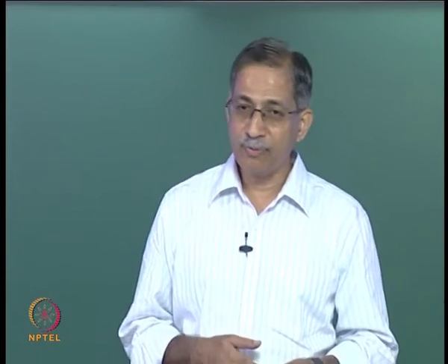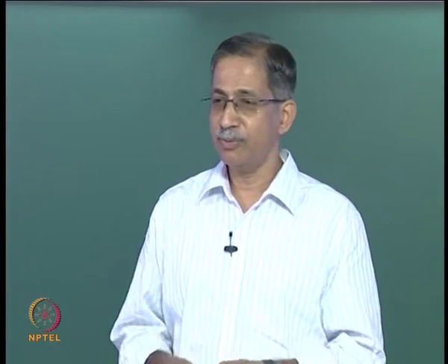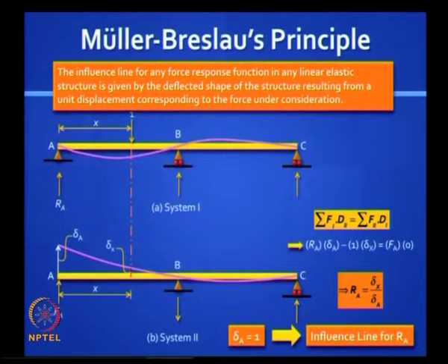And this can be proved for any response function. It could be applied to bending moments, shear forces, and so on. So it's a very beautiful principle called the Mueller-Breslau principle. So the statement would be: the influence line for any force response function in any linear elastic structure is given by the deflected shape of the structure resulting from a unit displacement corresponding to the force under consideration.